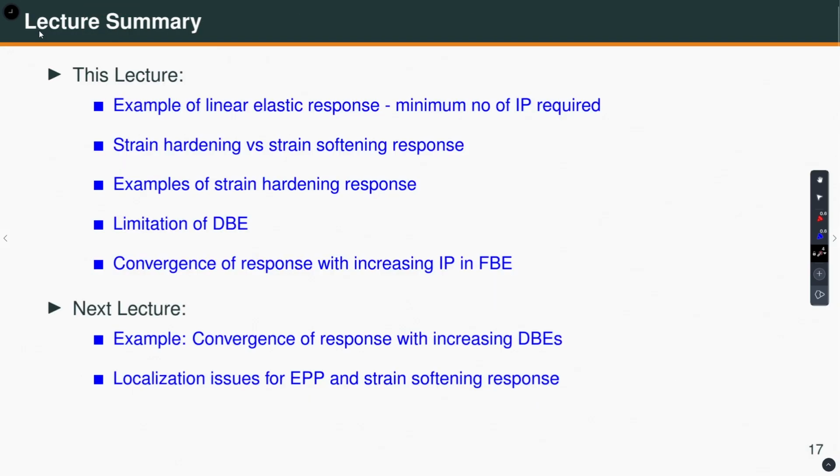With that, let me summarize. In this lecture, we have looked at a linear elastic response and we have demonstrated that you need at least 2 Gauss-Legendre integration points or 3 Gauss-Lobatto integration points for linear elastic response, be it a displacement based element or a force based element.